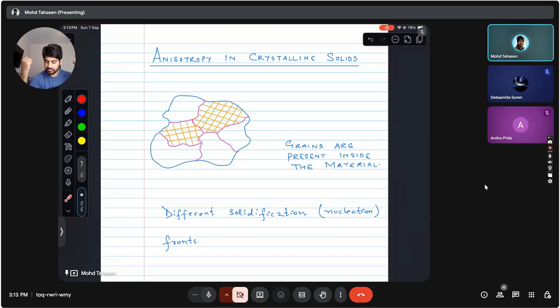There are stresses, and that's why the grain boundaries are regions of high stress. Along the grain boundaries there is no order. The material is not ordered anymore, and these boundaries are regions of high strain energy as compared to the lattice. That's how grain boundaries form.